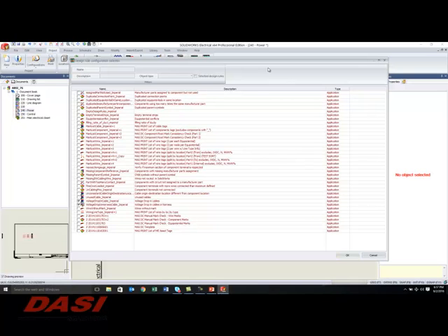Duct filling ratios. Anybody that's ever built a cabinet knows that duct filling ratios are one of those things that you would love to have, because in my world, in automotive, they would create those ducts, and every cabinet that you opened up had tie wraps or welding rods holding all of those wires into the duct because they overfilled it. Oh yeah, exactly. So this will actually calculate those ducts to tell you what the filling ratio is, so that if it's only 70% that you want, you can reroute those cables into other areas.